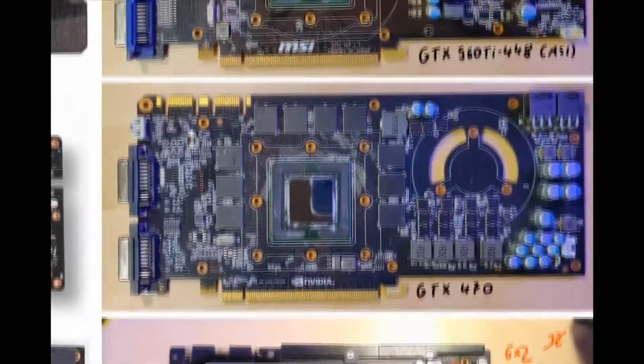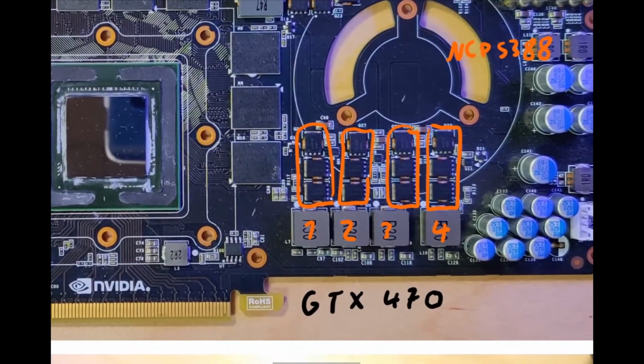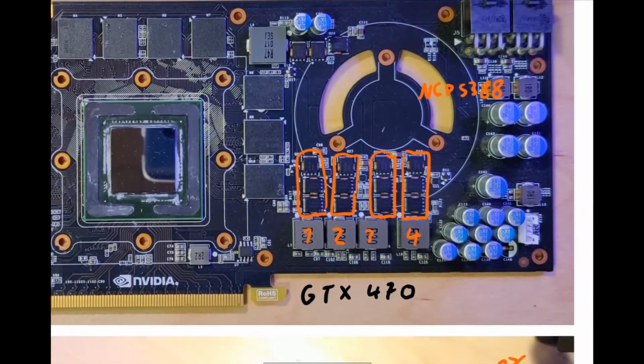And then another example of a VCORE VRM would be this. Here you have 1, 2, 3, 4 inductors, and it is actually also a 4-phase. This card uses discrete MOSFETs. And the PWM controller on the back, I think it is an NCP5388 if I remember correctly. But I did find the datasheet for the PWM controller on this card, and it was a 4-phase. So this is an actual 4-phase, and now I can also get into MOSFETs.